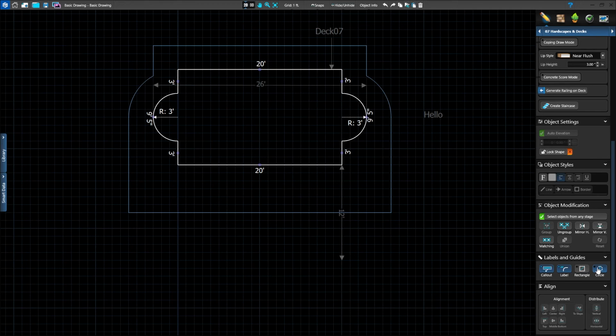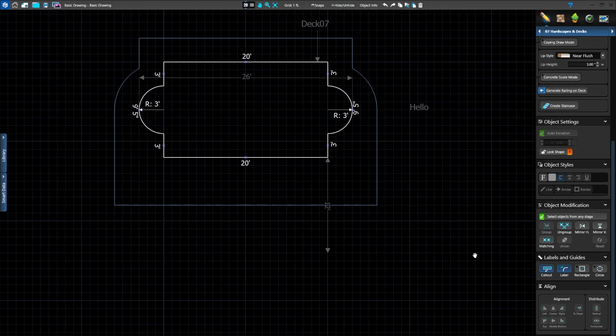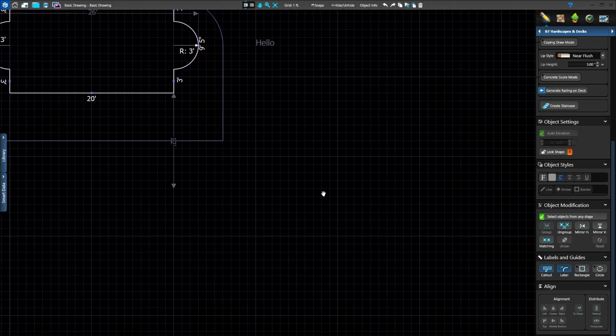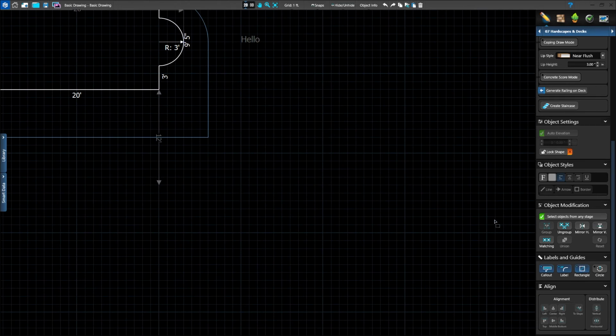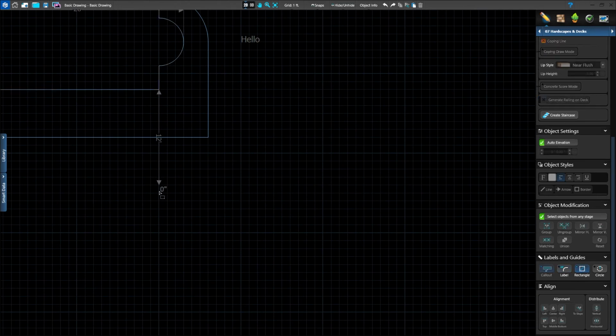We'd like to add a curving walkway, so we'll use the rectangle guide to mark the area. First, we'll pan the view of the grid by holding down the scroll wheel on our mouse. Then select the rectangle guide and left-click on the bottom arrow of our 12-foot measure line. We'll pull down 6 feet and right 30 feet and left-click to set the guide in place.